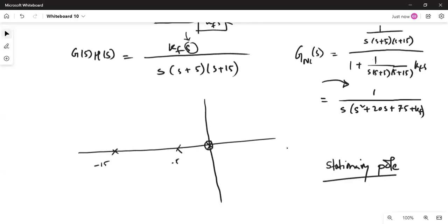So how will the root locus look? Basically, it is something similar to a 2-pole scenario. At -10, they will be merging together. Then one will be following the upper line towards infinity, and the other will be following the lower line towards infinity. So this is what we know from our idea of root locus.